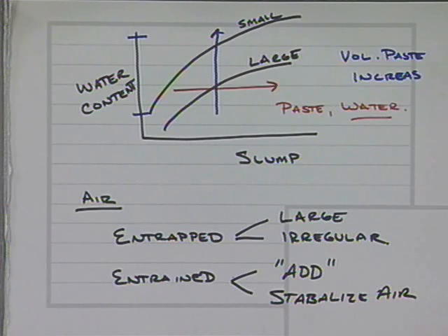It's going to provide a way that we can relieve some of the pressure that starts to build up when the water starts to freeze and expand. It's going to delay the time it takes that concrete to saturate, and it's going to be something that we can look at in a beneficial fashion.